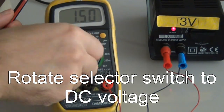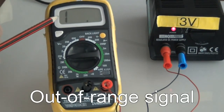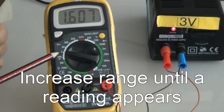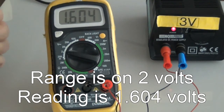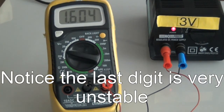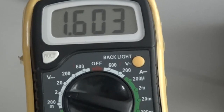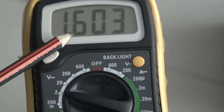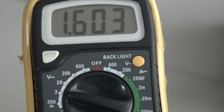We rotate the switch to the DC voltage range, but we have an out of range signal, so we have to go to a higher range until a reading appears. So the range is on 2 volts and we can read 1.604. Notice that the last digit is very unstable. We can see clearly that we have chosen the 2 volts maximum, but it reads 1.603 volts.